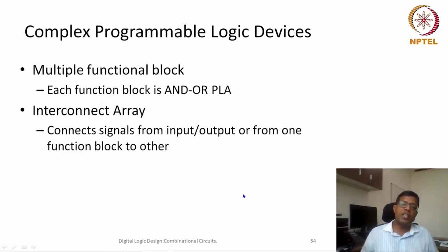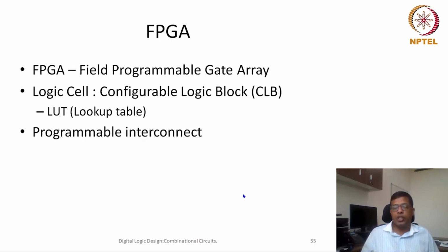This was not even sufficient; the CPLDs were able to make something more programmable, but even more programmability was required. So then we resorted to something which is field programmable, so that we can program it again and again. Field is usually electric field here. So basically this is programmable using electric field or voltage or current. Now here you call it gate array, because there is some basic logic which has been repeated again and again. So here the basic unit is the configurable logic block.